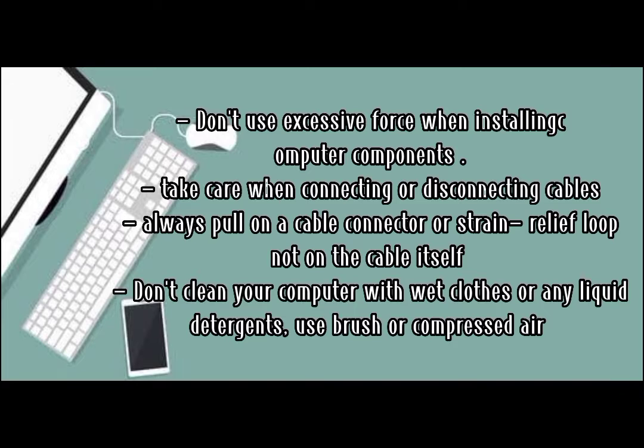Take care when connecting or disconnecting cables. When disconnecting a cable, always pull on the cable connector or strain relief loop, not on the cable itself. The last one is, do not clean your computer with wet cloths or any liquid detergents to avoid accidents and also to avoid electric circuits. Instead, use a brush, compressed air, or a blower in cleaning the computer system.